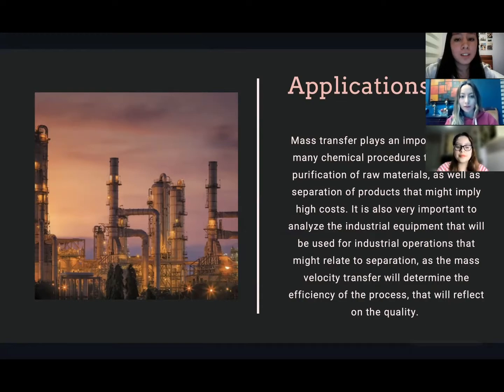In this project, mass transfer is applied to apple dehydration, in which apple slices will be left in sugar solutions, and then by gas oven and microwave oven heat transfer, the dehydration process will take place. The loss of water during the process will be analyzed as a consequence of water transfer between the apple slices and its surroundings.